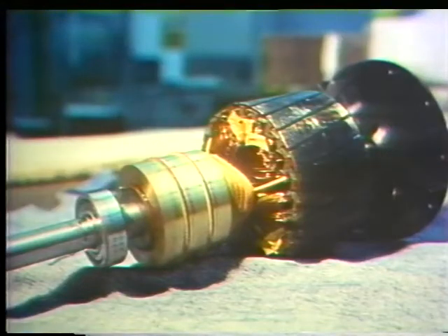Up until now, we've been talking about what makes a squirrel-cage rotor turn. But what we've said also applies to a wound rotor. A wound rotor has coils that are made of wire. The next thing we're going to look at is a wound rotor. Wound rotors are more expensive to make than squirrel-cage rotors, so they are not commonly used, but because it's possible to control the speed of wound rotor motors, they are sometimes used where speed control is necessary.